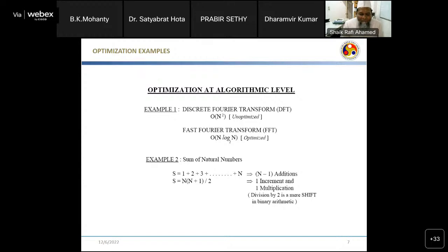Any other doubts? Professor Sek, do you have any idea about the advantage of DA over CORDIC based design, because both are multiplier-less? CORDIC will normally be used wherever trigonometric functions are there. If it is without trigonometric functions, then DA is preferable. So basically, whenever you have a trigonometric problem, then CORDIC will be better. Right.